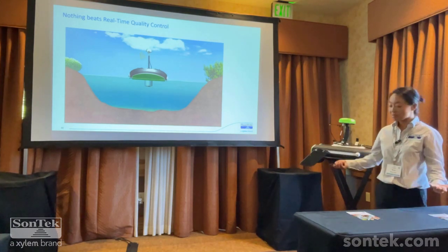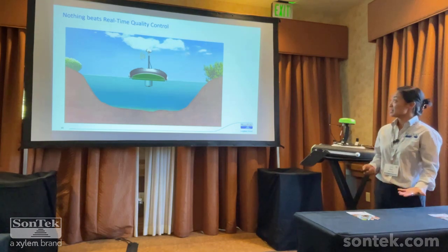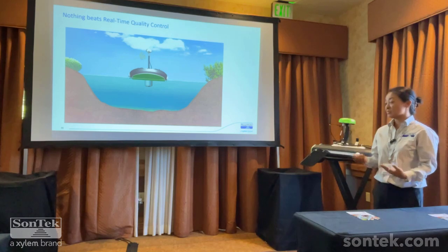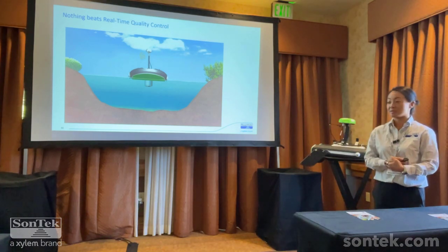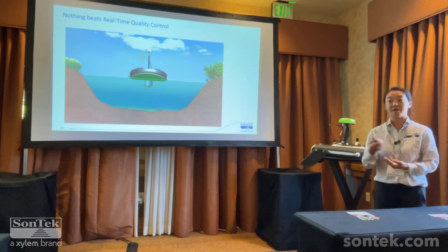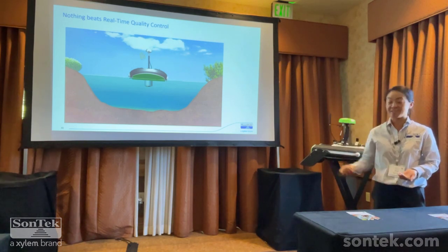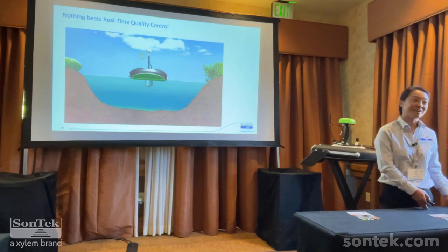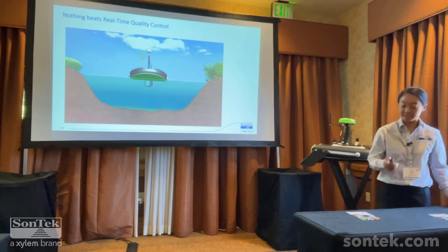Okay, I guess the takeaway message from all of this information is that really nothing beats real-time quality control. When you're at the field site, if there are things that you can do to improve your data, or you realize that your bottom track is missing, that you do need GPS, and you realize you haven't calibrated your compass, it's too late once you get into the office to realize that. You will have needed to do that in the field.